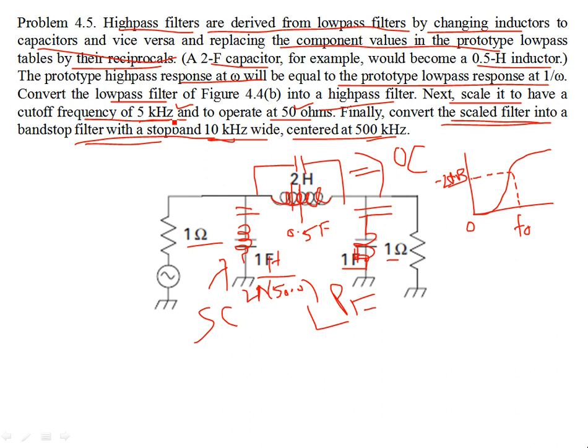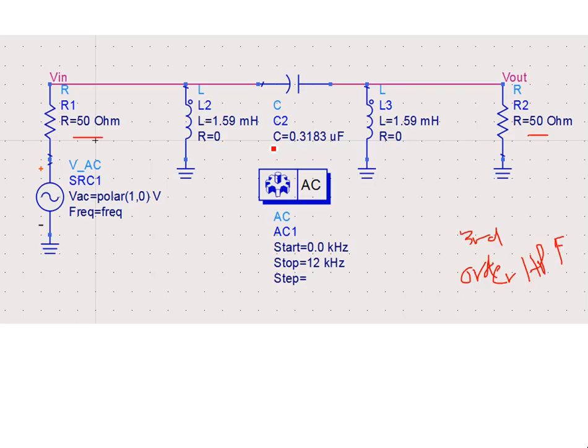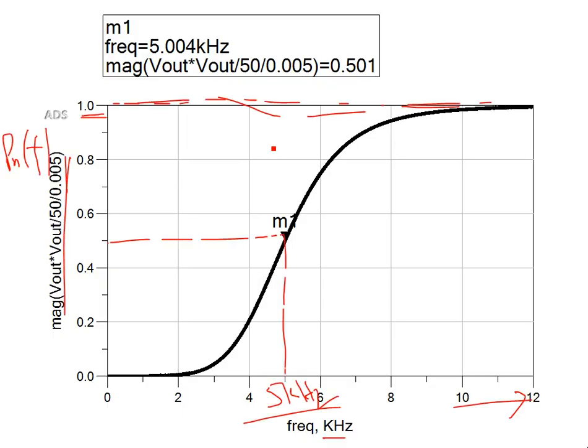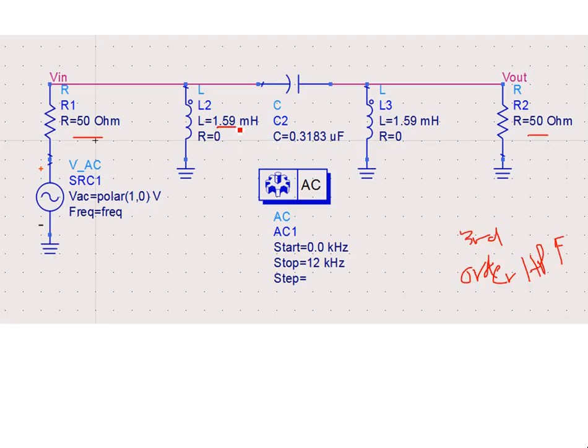So on either side, we are going to have twice of 5 kilohertz, that is 10 kilohertz wide stop bandwidth. Okay, so that means you have to divide this inductance by 2, because inductor and capacitor are going to contribute equal reactances. So you're going to have a capacitor over here, and then from 1/(100 LC), you have to consider 2 pi if you're considering the frequency in hertz.